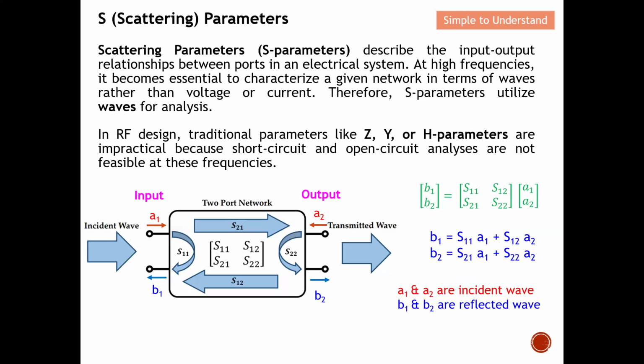So at very low frequency, which means I'm going to have a very small number for the frequency F, the total reactance will be very small. However, imagine this, when the frequency keeps on increasing, it becomes high frequency, and the frequency becomes a very huge number, which makes the reactance of the inductor not a small number anymore.